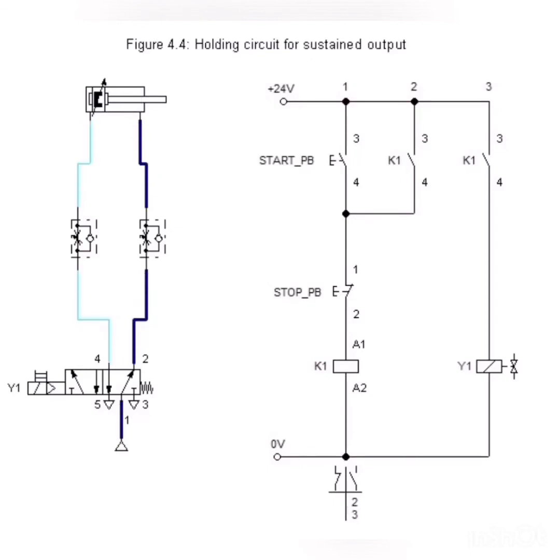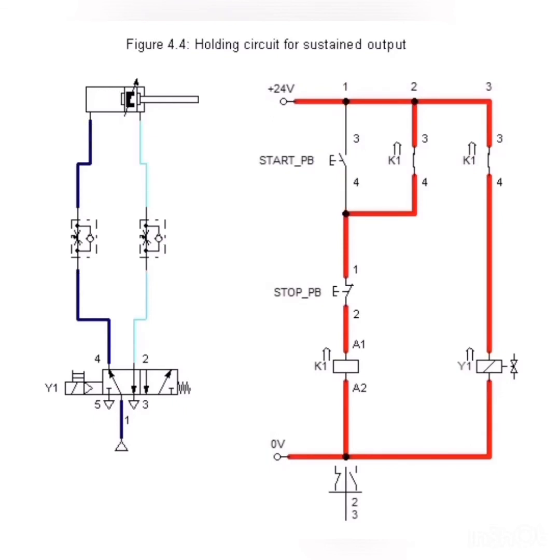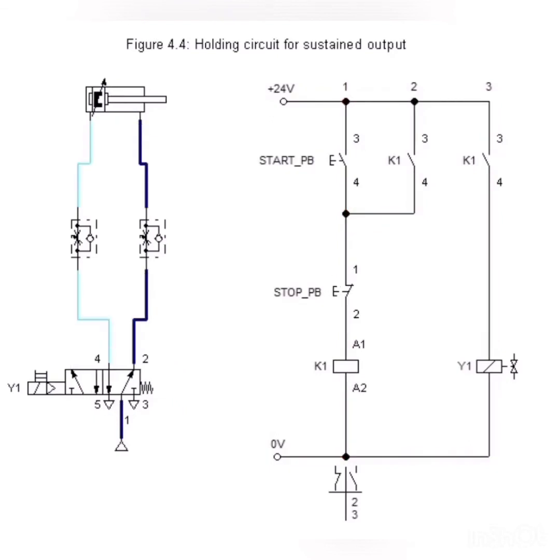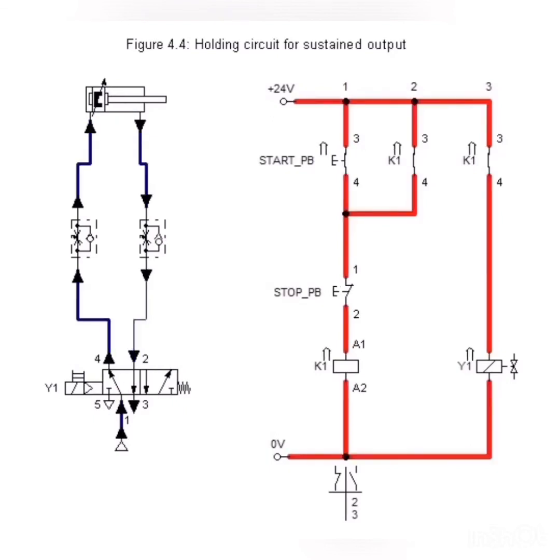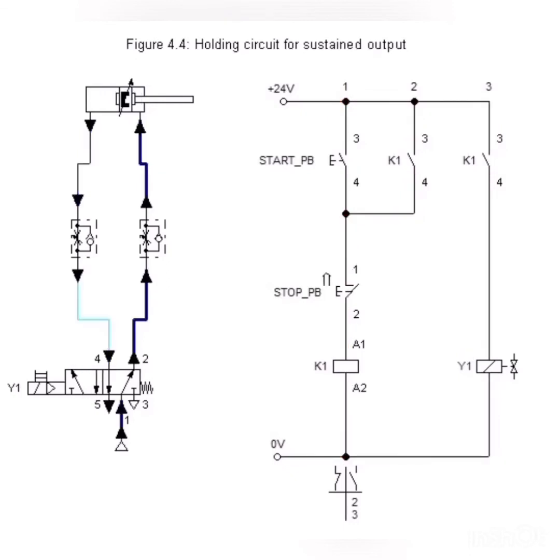When the stop is pushed, the valve block changes its direction from right to left and it gives way to the airflow to go through it. Therefore, when there is airflow, the cylinder will extend from the retracted position. The electrical circuit shows its operation. As the circuit contains the holding circuit, the output remains in the same position until a different input is given.